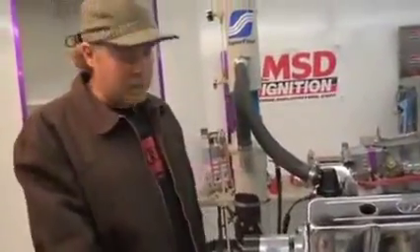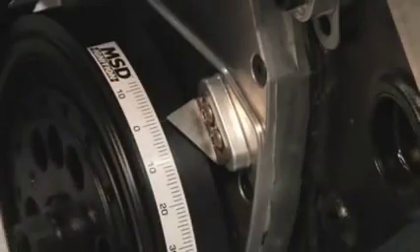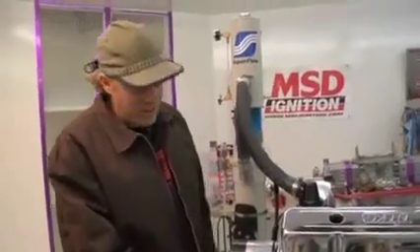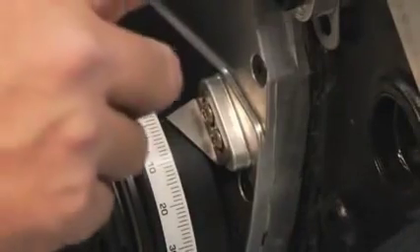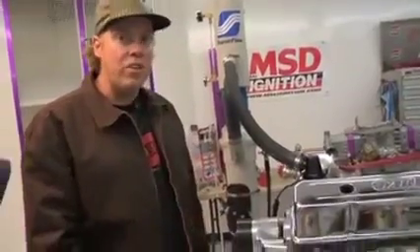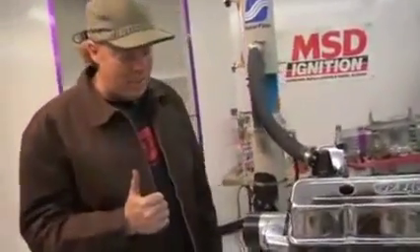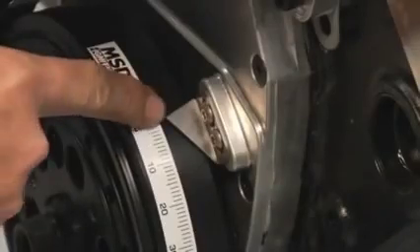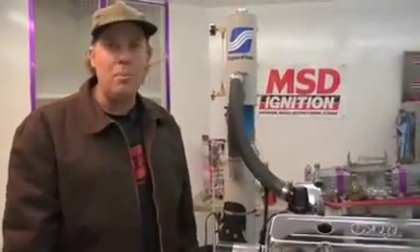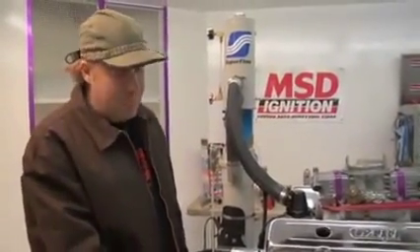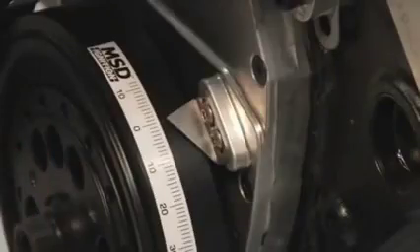Ignition timing is typically read from a mark that's on the harmonic balancer on the front of the engine, and the 0 point represents top dead center from the number 1 cylinder, in between the compression and power stroke. This 0 mark will have been set by the factory on your engine, or perhaps by the machine shop that built it for you, but it's critical that that mark be set exactly top dead center on number 1.